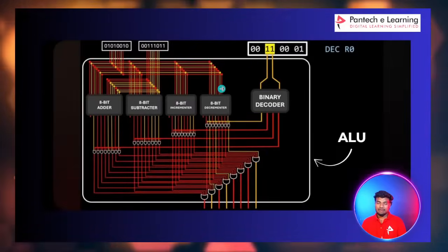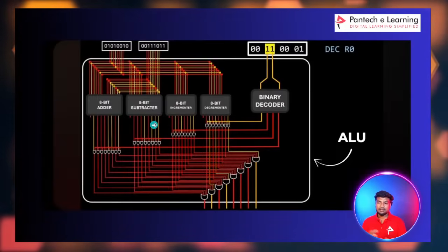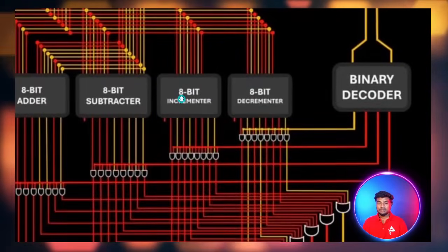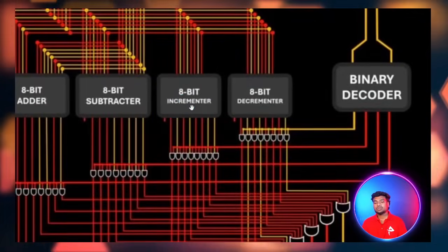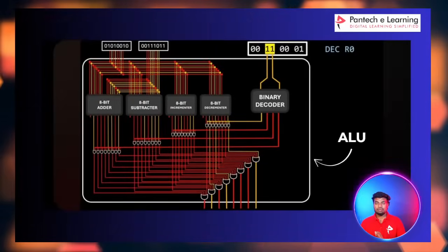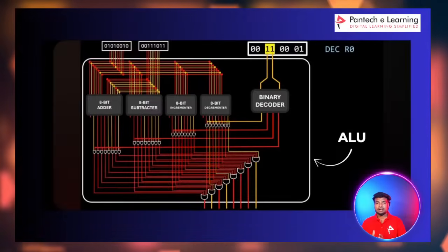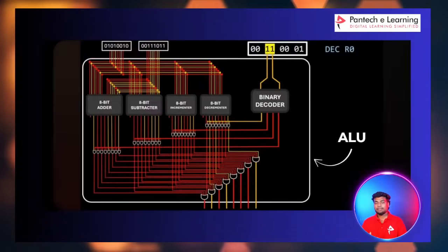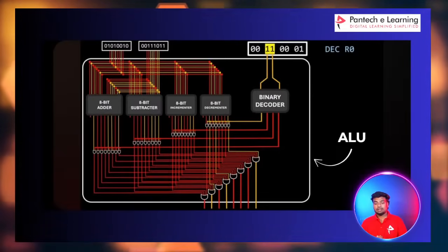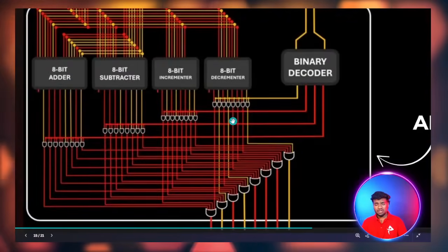After writing the RTL code, I convert the RTL code into gates. It will look like this. Inside the 8-bit increment, there are some logic gates. That's what I was telling you yesterday. We write the RTL design code, and then we have to test the design code by using the SystemVerilog language. This is front-end work. After that, we have to convert the Verilog design code into gates, like XOR gates and OR gates.